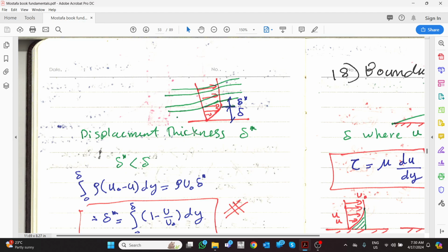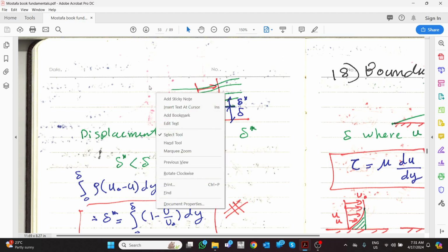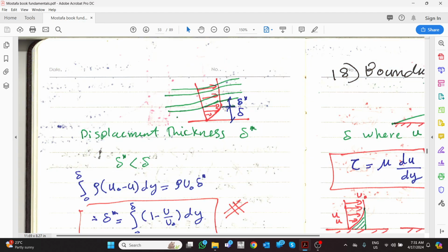The displacement thickness is when we have a change in the u from the wall till here, the potential flow seeing this area as a block. So the stream starts not to be potential flow. It is getting affected by another effect, where the stream is going to bend like this, then it will continue normal. This bend is named displacement thickness, and originally this displacement thickness for the potential flow above is less than the boundary layer thickness.